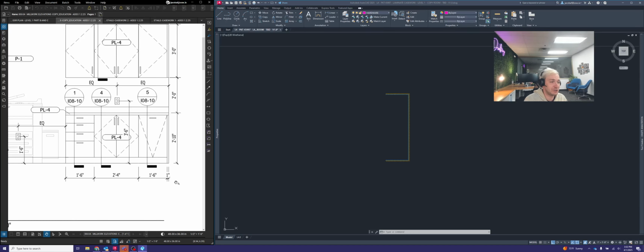So we're going to go 1 inch, 1'6", 2'4", 1'6". So I'm going to add those up here on my calculator real quick. And it should be 65 1/4 if you include that 1/4 inch overhang on the finished end.